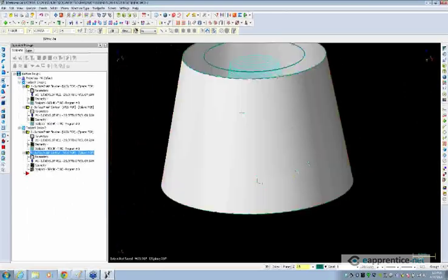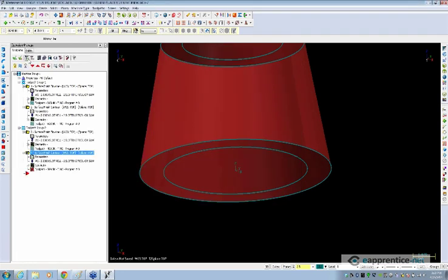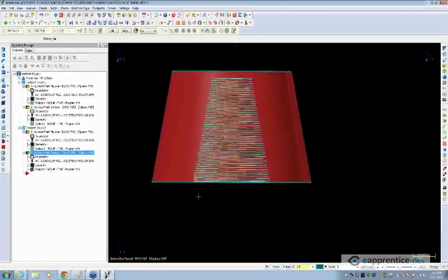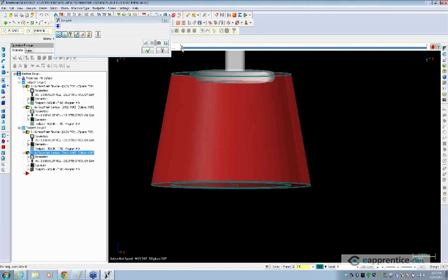Now, the other thing that we can do, instead of worrying about start length, is enable spiral limit. What spiral limit will do is, depending on your value that you put in here, any motion with a slice that is less than this value is going to get turned into a spiral. So here our maximum step down is 50 thou. We want to set our spiral limit the same, and what will end up happening is the toolpath will get generated with no step over marks. Now it's essentially just like our flowline toolpath. It's just becoming helical kind of spiral ramping motion that does our undercutting.